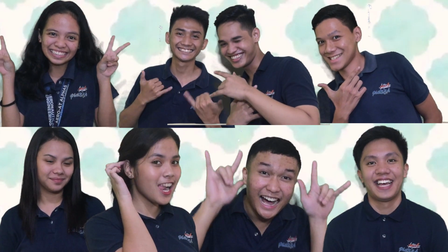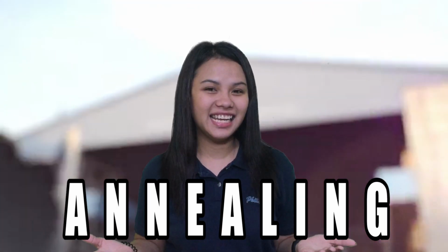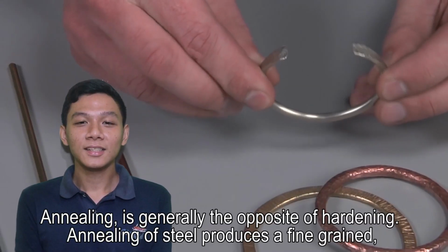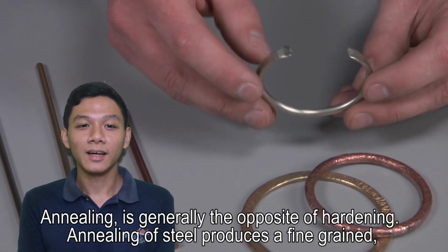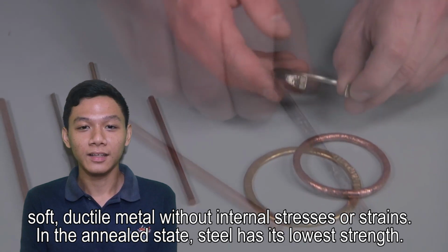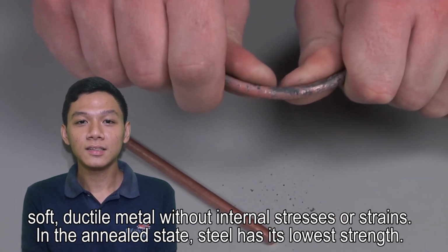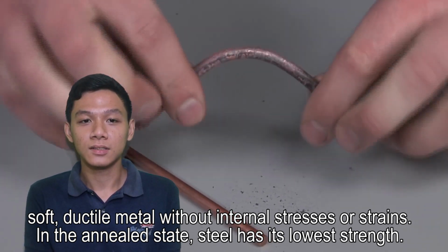For today's video, we're going to show you the different types of heat treatment, particularly normalizing, annealing, and case hardening. First things first, do you know what's the opposite of hardening? Annealing is generally the opposite of hardening. Annealing of steel produces soft, fine-grained, and ductile metal without internal stresses or strains. In the annealed state, steel has its lowest strength.